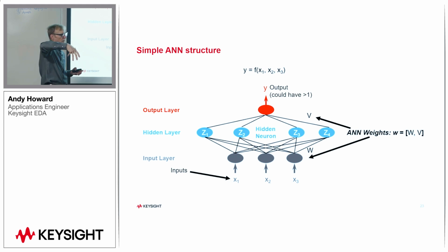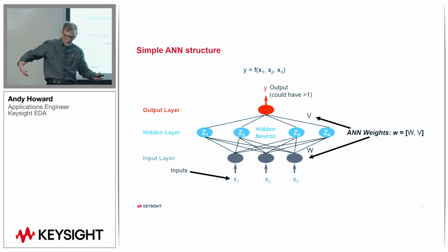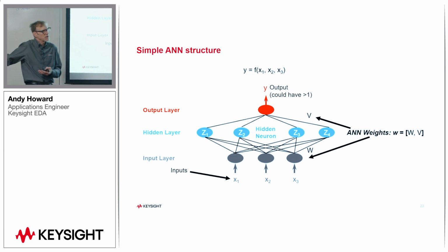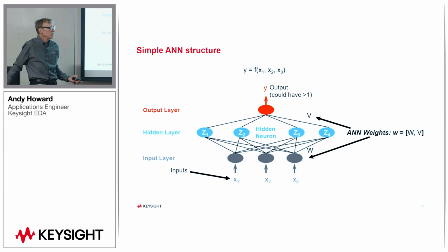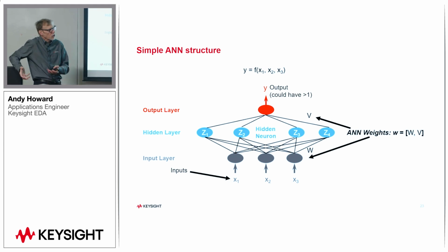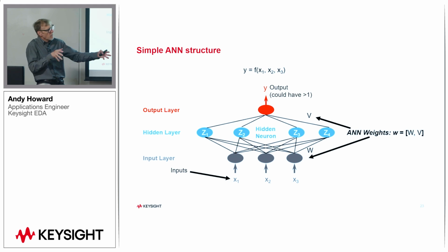So I have this irregular collection of data that's based on this irregular sweep of a bunch of parameters. And I want to be able to take all this and use it in an optimization. And I can't do that because I have to be able to interpolate the data. I don't know how to do that. So the ANN is a model of the measured load pull data, and that enables me to interpolate it very accurately and very efficiently in an ADS optimization.